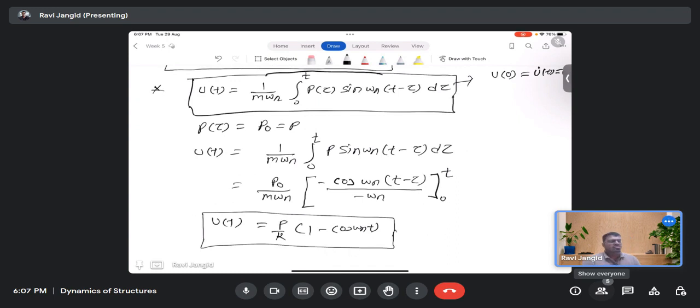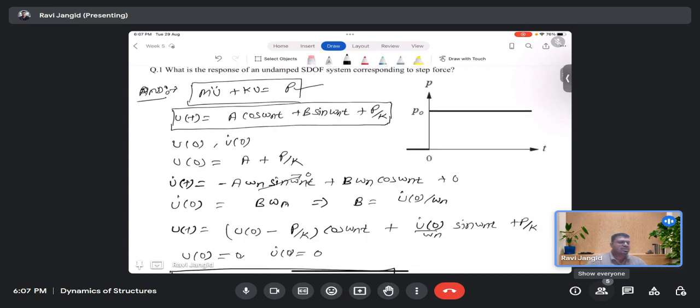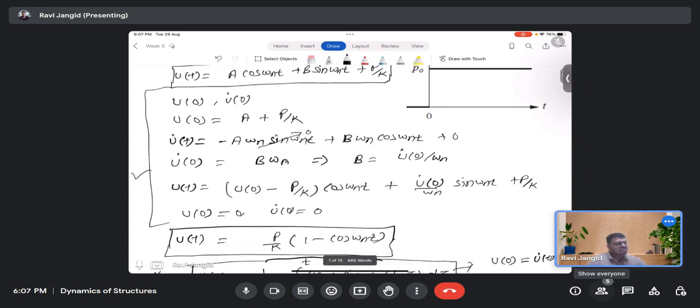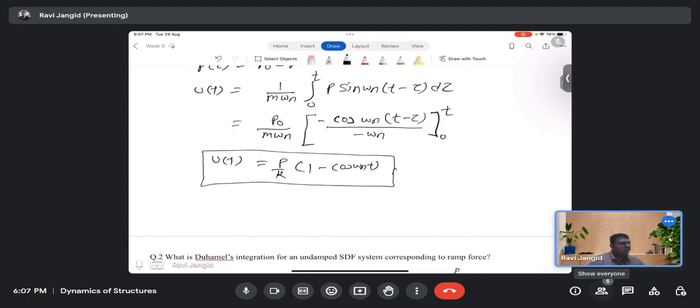For a simple system with a step kind of function, this solution was not so problematic. But instead of the step function, if we have some other function, let us suppose a rise time, then a straight portion, then a lower, in that case by using the Duhamel integral you can find the solution very easily. The Duhamel integral is nothing new, it is only a technique, a simpler way to find the solution of the equation for different types of problems.